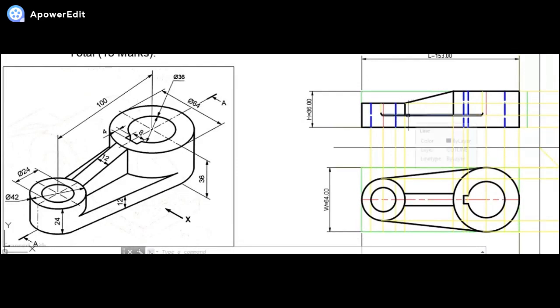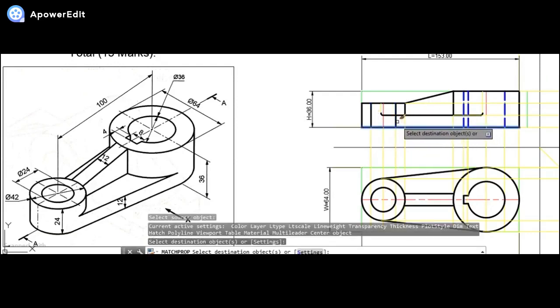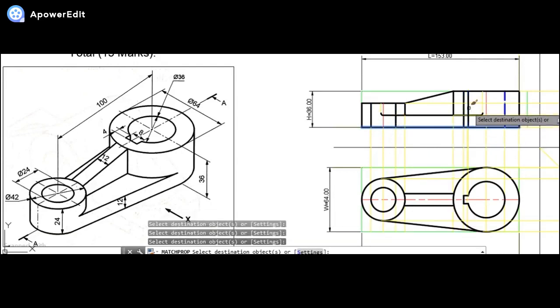As we see the sectional front view along AA, let us first convert the hidden lines, which will be seen as dark lines to us. So this is the one, this one, this one, this one, and this one. Second, we need to remove the edges which at that particular instant won't be seen to us. Very clearly we can see these edges won't be seen now. So this one, this one will become one entire area. This one won't be seen, this one won't be seen.